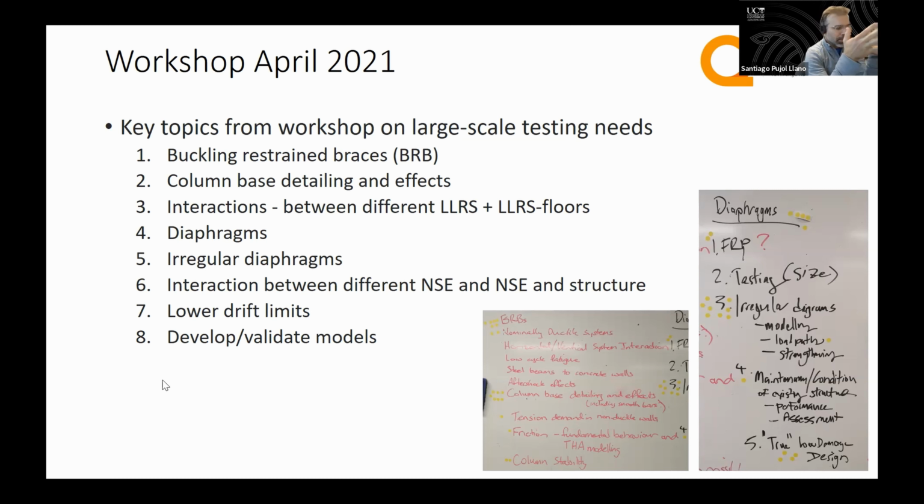Of course, one of the main issues here to keep buildings functional, to make sure that the building works as a whole, is that, as item 6 suggests, the non-structural elements and the structural elements need to work well together. That, by the way, may imply that we design buildings for lower drift limits. At least that's an option, as implied by item 7.